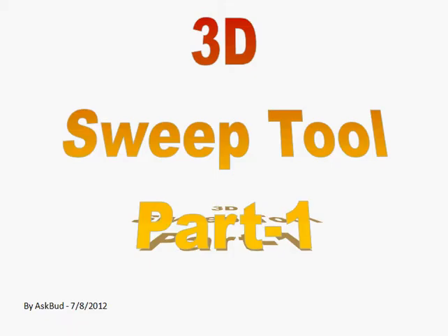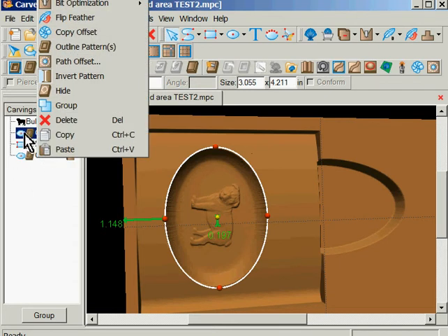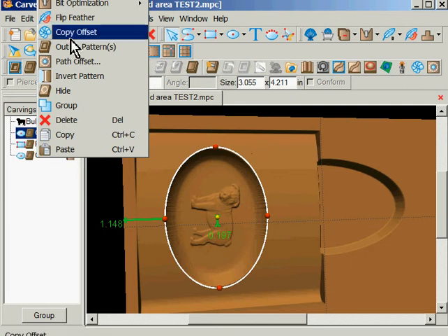So you don't have to question exactly what it is and ruin something. If you have it highlighted here in your carving list, right click and you can see what's applied. If a draft would be applied, whatever you applied would show up on this chart. On the merge, I don't have to go to the merge thing to see. I can see right here. The same thing with clip carving. I will know whether it's inclusive or exclusive right there.